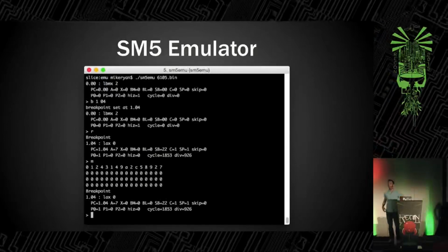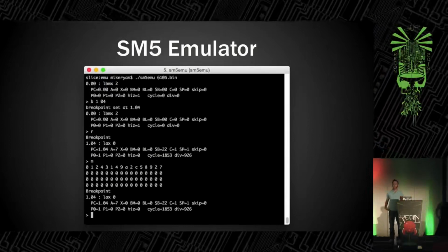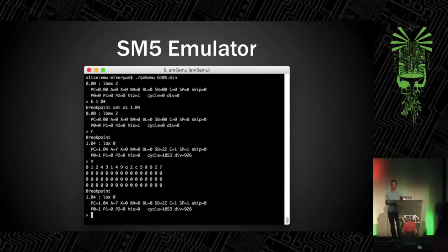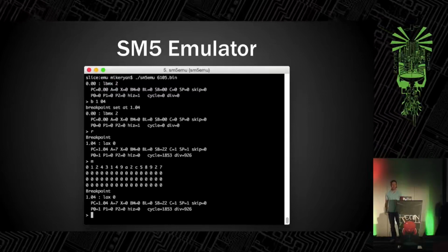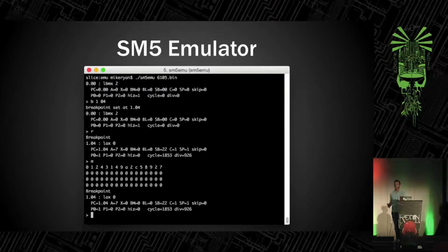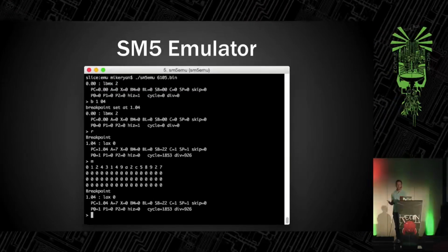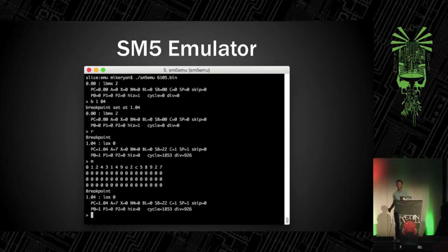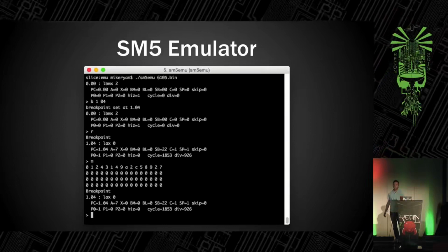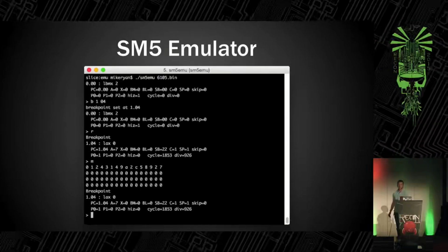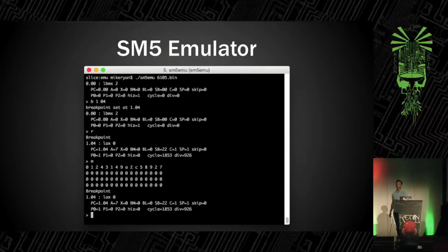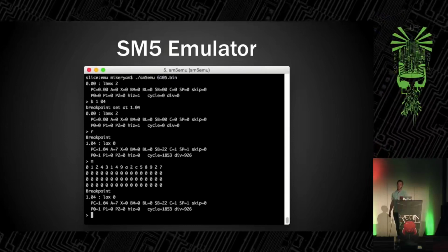But this was pretty opaque code. I'm not terribly good at reverse engineering, despite giving a talk here, and I'm much more of a debugger type of guy, so I wrote an SM5 emulator based on these data sheets, and we were actually able to run a simulation of this chip pretty effectively. It's a decent little emulator. It's got a built-in debugger, code and memory breakpoints, memory viewer and editor. Right now, I'm working on undo functionality, since we know that's very important.